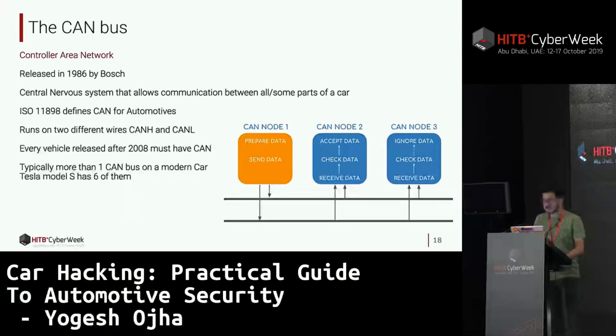The sensors and the ECUs have a transceiver that you see here. The transceiver is actually responsible for either accepting or rejecting the packets. The CAN node generally consists of 3 different components: a transceiver, a CAN controller, and a microcontroller. A transceiver converts the data stream of voltage from a CAN bus so that other electronic units can understand it, whereas the controller actually acts as a link layer between the nodes.